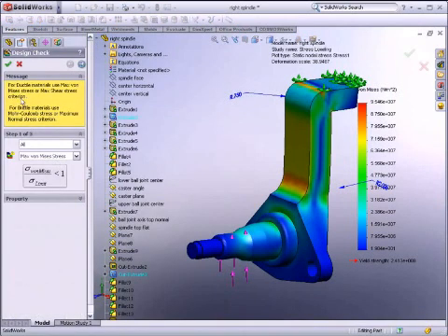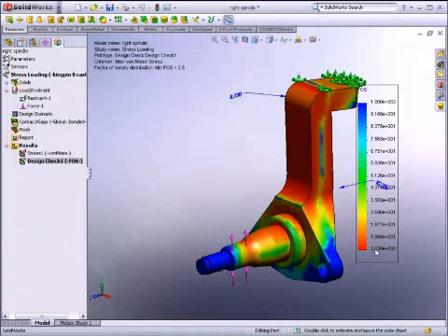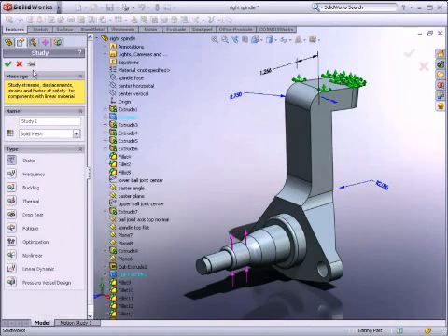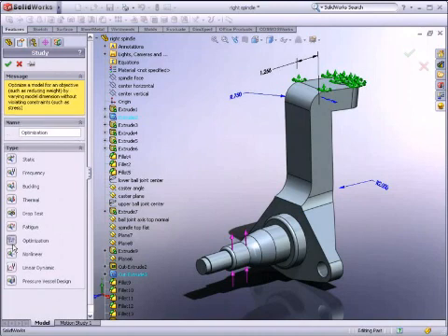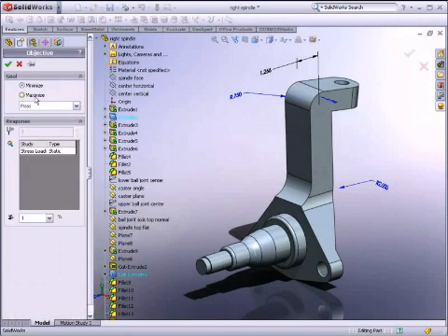You can then determine the lowest factor of safety, which for this example is 2.5. This means that there is room to reduce the mass in the design by changing the dimensions while retaining its structural integrity. With the criteria defined, the optimization can be carried out, as SolidWorks Simulation now understands what loads must be applied during its iterations.